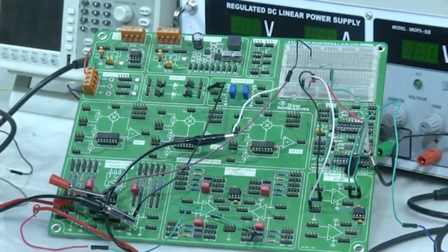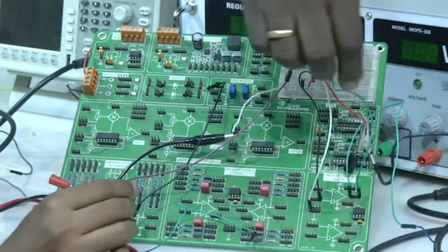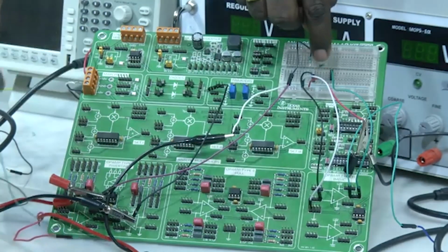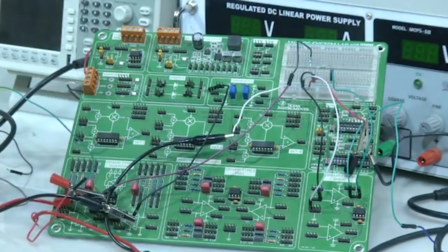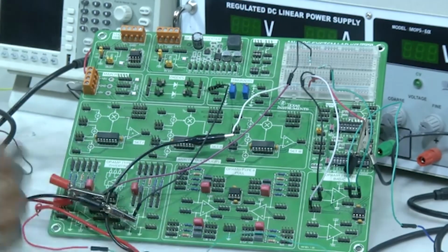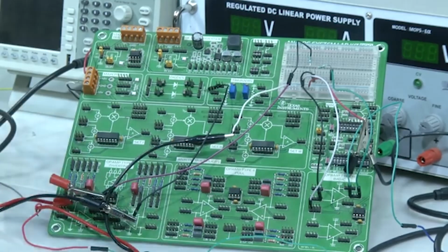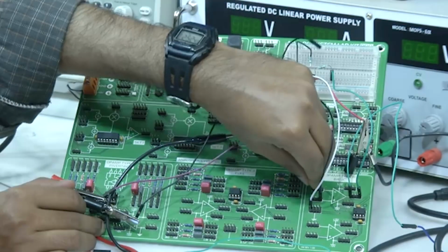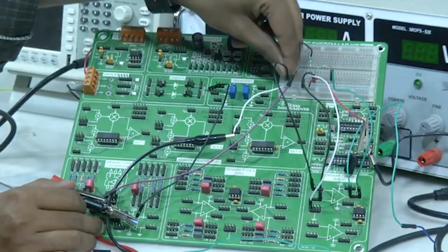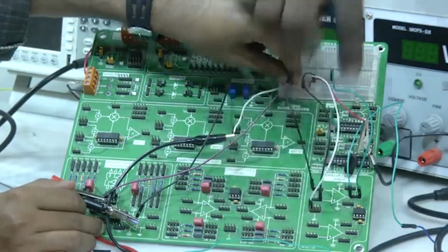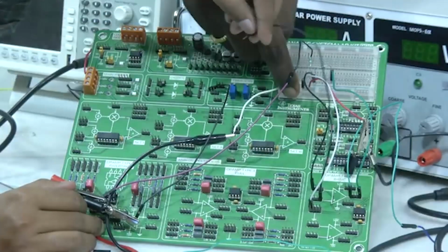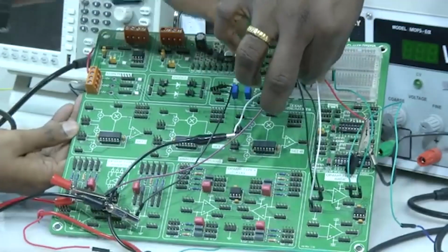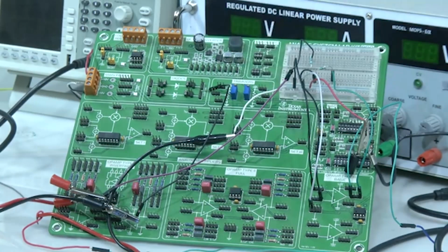Right. So we made connections to the positive terminal. We also made a connection to the feedback resistor. What about the negative terminal of an op amp? The negative terminal of an op amp should be connected to the ground in this case. So, we will take one more jumper, the ground is just below that. From the negative terminal we are connecting to ground, or we can also connect it at this point too, because we already connected this ground using a white jumper wire to this board.